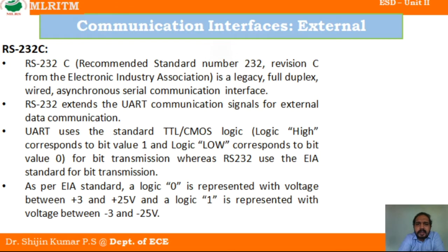As per the EIA standard, a logic 0 is represented by plus 3 to plus 25 volt, and logic 1 is represented by minus 3 to minus 25 volt. So we need a converter to convert from TTL or CMOS logic to EIA logic.